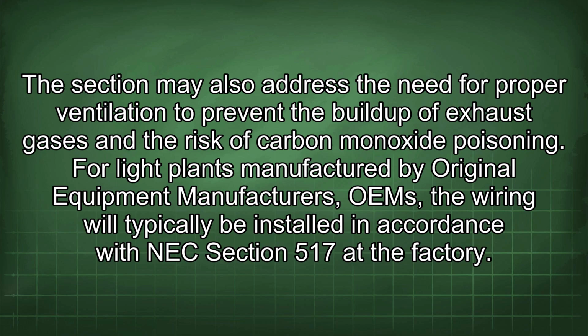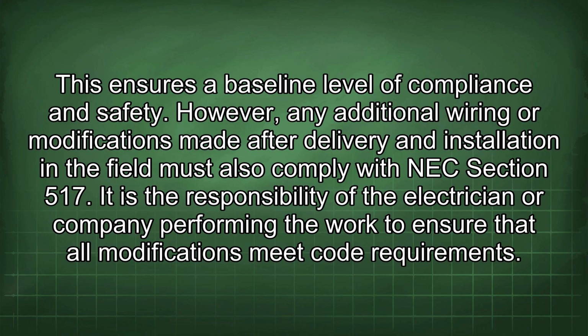For light plants manufactured by original equipment manufacturers, OEM, the wiring will typically be installed in accordance with NEC Section 517 at the factory. This ensures a baseline level of compliance and safety. However, any additional wiring or modifications made after delivery and installation in the field must also comply with NEC Section 517. It is the responsibility of the electrician or company performing the work to ensure that all modifications meet code requirements.